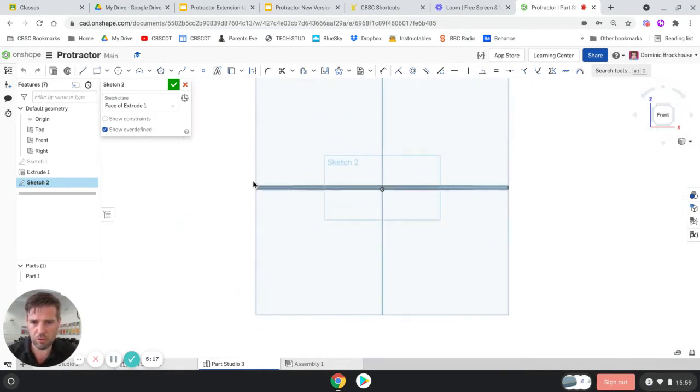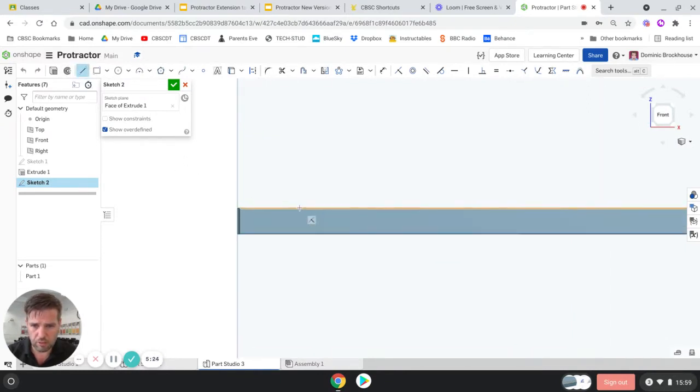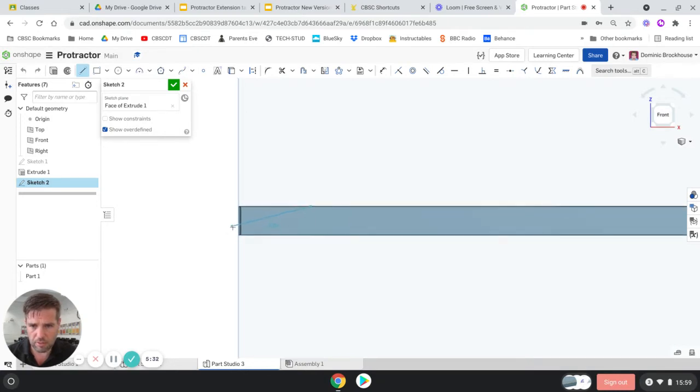Now we're going to scroll and zoom right in on the left hand side here, and then use the line tool to draw a triangle, and it wants to start from the top. We could lock it onto the top, constrain it to the top, and then draw it a little bit longer than it needs to be. Click, click, and then connect it all up and go click. So that's my triangle. Ideally, the length of it should be about 3 millimeters long and about 1 millimeter high.